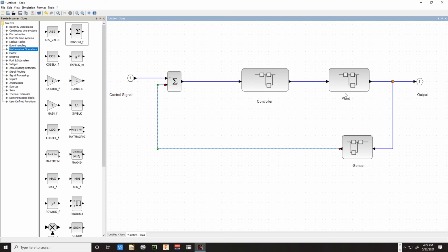Or it's too cold in the house. It turns on the heater inside the plant, which is the house, and the sensor picks up the temperature rising. When it gets within a certain range of this, the controller sees that difference, says, okay, the difference is small enough now, turns that off. So this is a standard form of a simple first order controller that uses feedback.